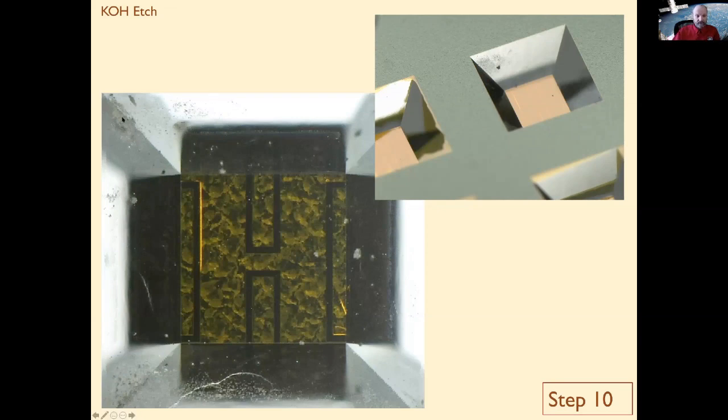And then you might think, oh, this is kind of an interesting crystal etch. This is an optical illusion. I refer you back to the right side picture. This is what it really looks like. Okay, since these surfaces are very reflective, it's like a house of mirrors. You got two mirrors at an angle to each other, right? And then the light reflects funny, and when you look at it in a microscope, it kind of looks like you have this bizarre structure here. But that's, like I said, an optical illusion, and you can convince yourself of that when you're looking at structures on the microscope by tilting the wafer a little bit. Sometimes you can tell that way, or try different illumination schemes on your microscope.